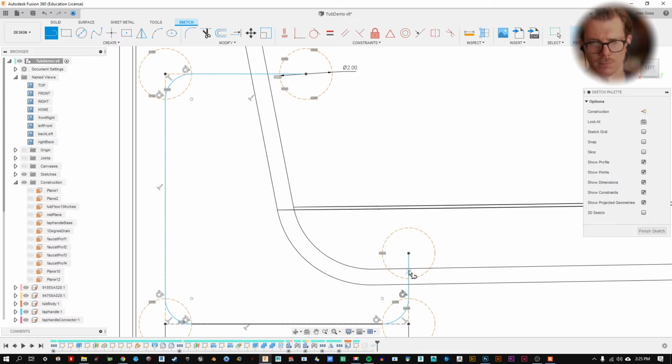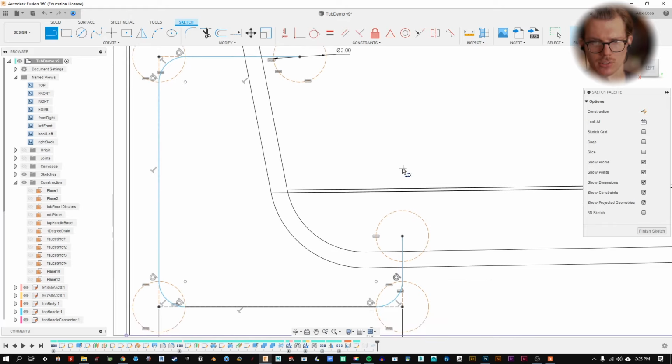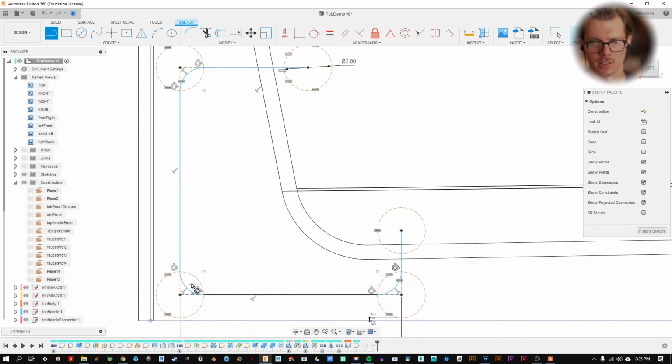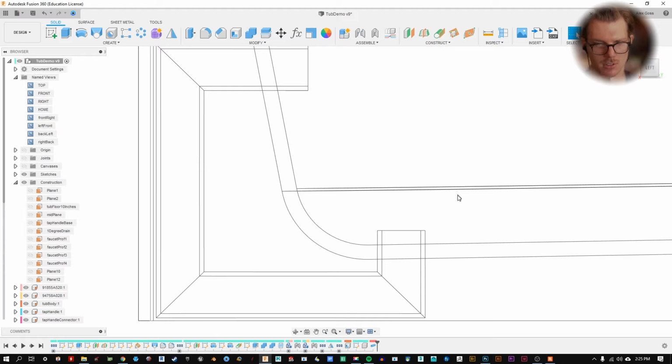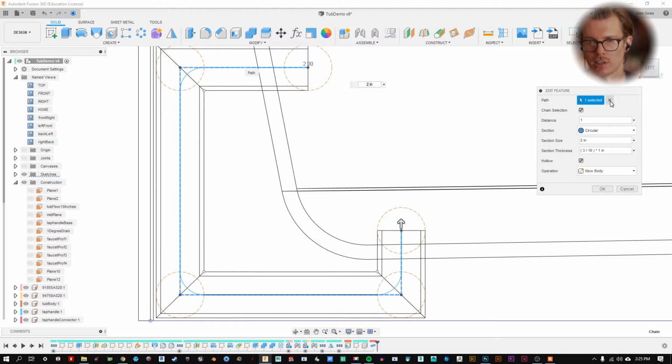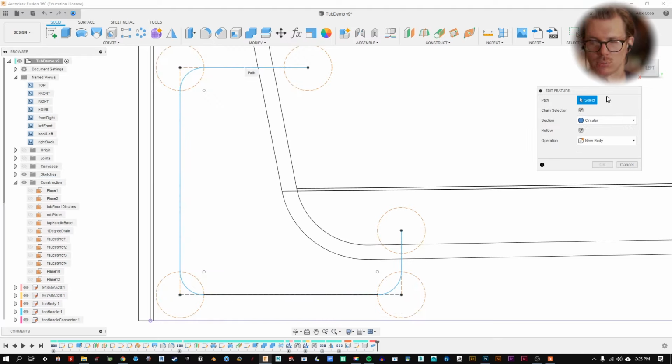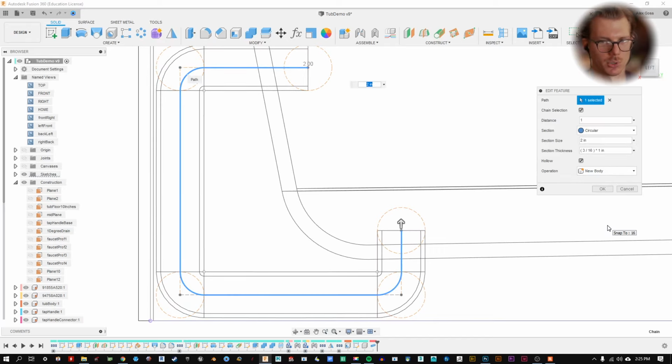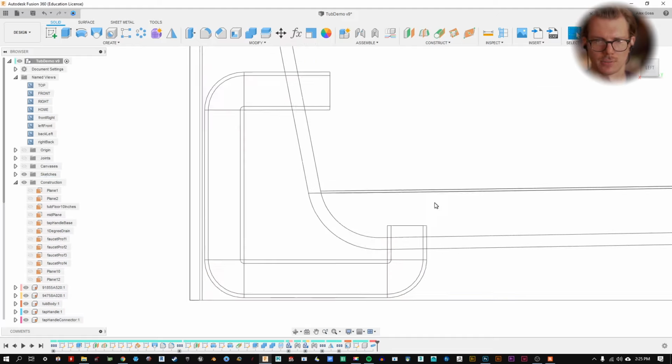So now we've rebuilt our pipe curve, and now we've added some fillets. So let's hit Finish Sketch. Nothing changed because we need to tell Fusion we've got some new geometry for it. So we can empty or press that X for a new path, and now there we go. Beautiful, curving, non-self-intersecting pipe. And let's hit OK.